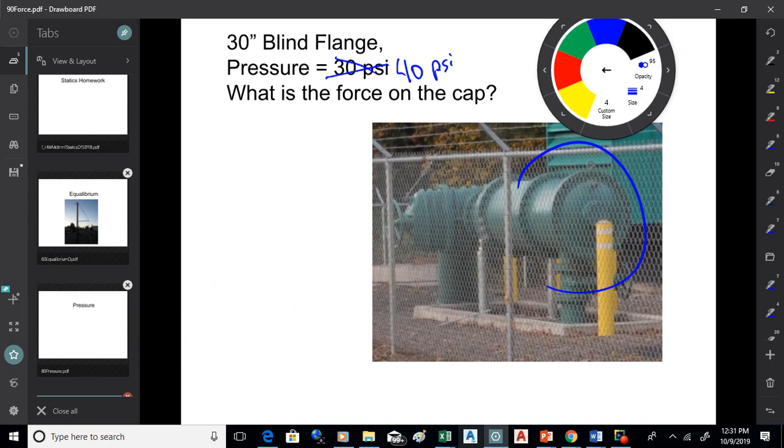A little over 28,000. Now, that's a different animal. I mean, 147 pounds out here, okay, whatever, but 28,000 pounds, that gets my attention. So be aware of this. If you got big mains, if you got dead ends on them, you got a heck of a lot of force.